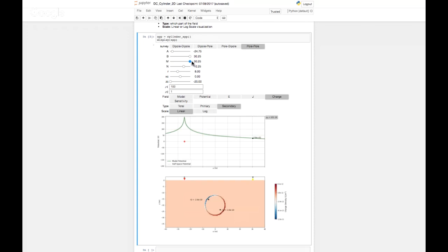It's not the best example for illuminating this, but the apparent resistivity is actually larger than the background, even though this body is even more conductive. We actually exceed 100. Now you can understand where those pictures were coming from earlier. The reason is that this M electrode here is actually closer to these positive charges, so it's increasing the potential, hence the apparent resistivity is increasing.